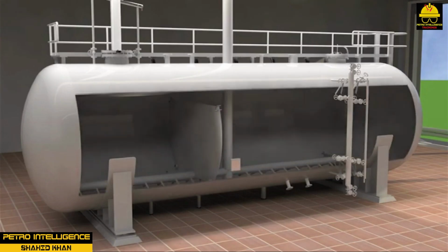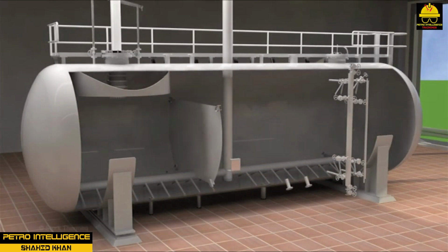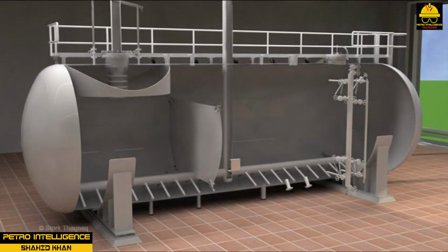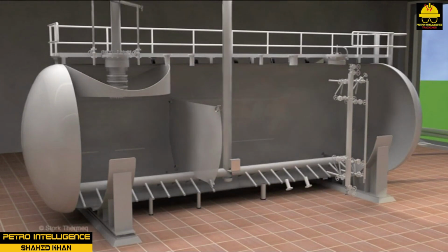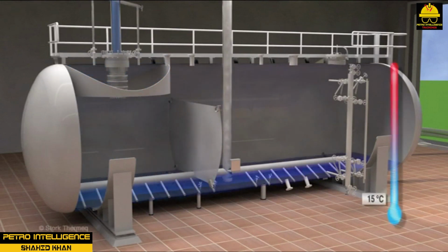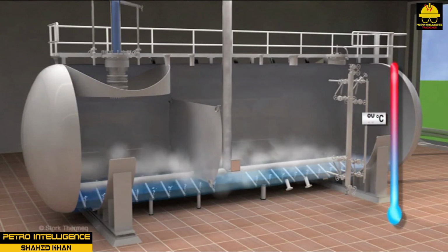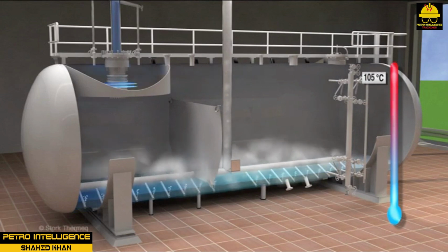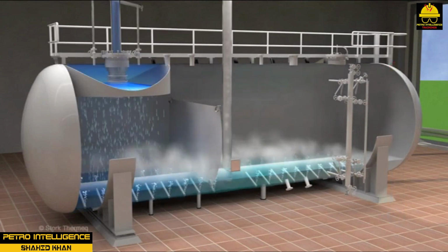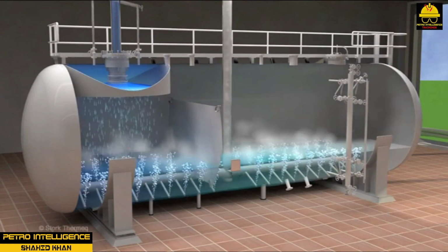De-aeration. A deaerator is a device used to remove air from water. The deaerator is typically located at the end of the condensate return header and is used as the primary boiler feed source. Dissolved oxygen is a serious problem because it leads to boiler system corrosion. The deaerator is designed to remove dissolved oxygen by heating the water with steam.